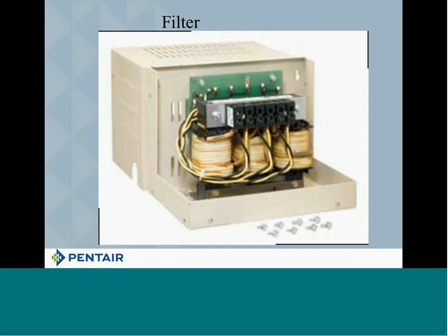It is a set of coils, the same as we saw before, only now we're also going to add a capacitor pack to it. And so we're going to run each one of those through a capacitor pack and then to the motor. Basically, your filter or reactor gets hooked up on the discharge side of the drive. So you hook up where you would go to your motor, bring it out, put it to a reactor, and then run it down to the motor. Or hook it up to a filter and then run it down to the motor. That's what your filter reactor is going to do for you.